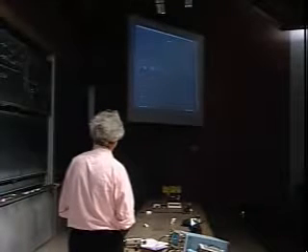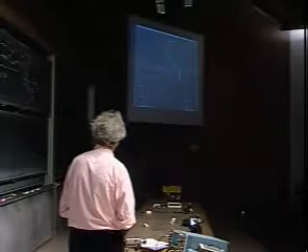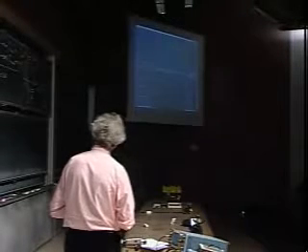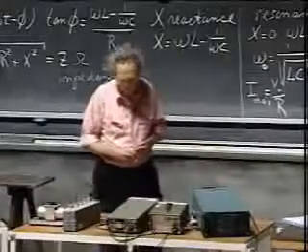To show you the effect of R, I will double R now, and I will leave everything else alone, so the resonance frequency will stay here, but of course the maximum current, this high value, will now come down. Because, you see, at resonance, this value is V0 divided by R, and since R goes up by a factor of 2, you will see that the maximum current will go down by a factor of 2.